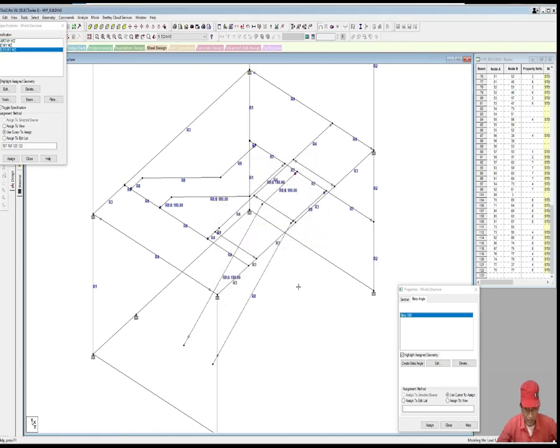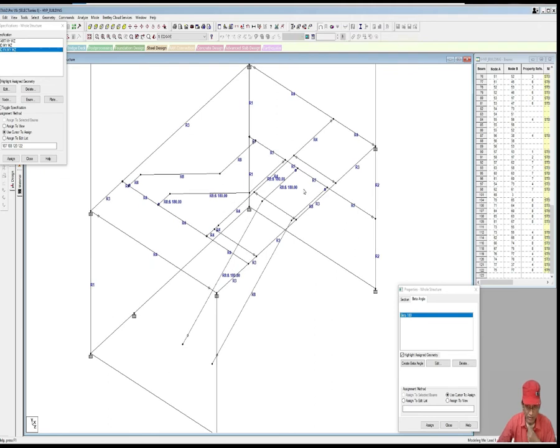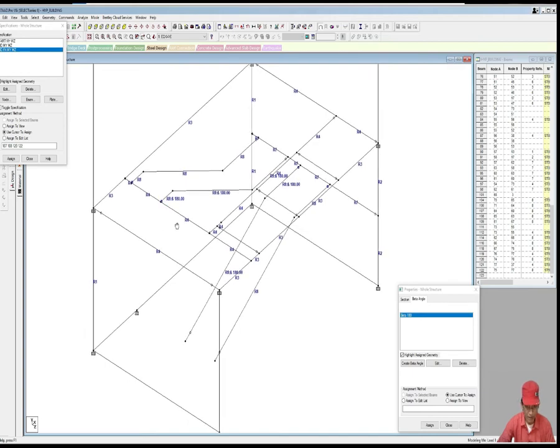Assigned. So it will prevent the staircase from absorbing any lateral load. For this part, while detailing the connection, you have to put a slotted hole for the bolt so that the staircase is free to move whenever the structure is subjected to some kind of lateral load.